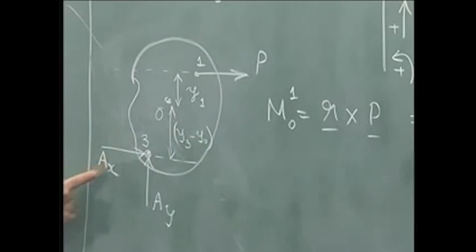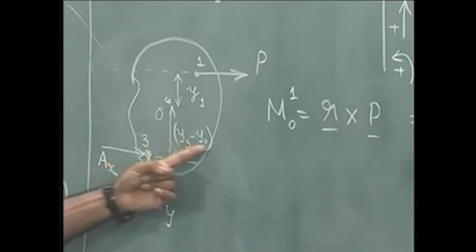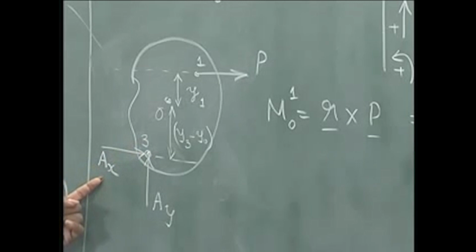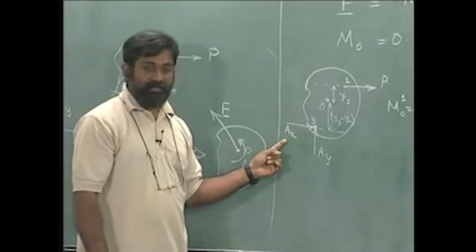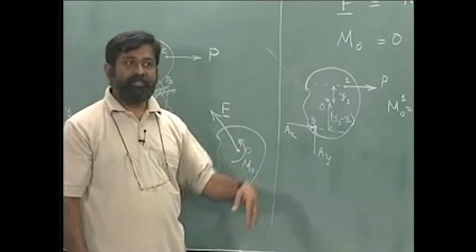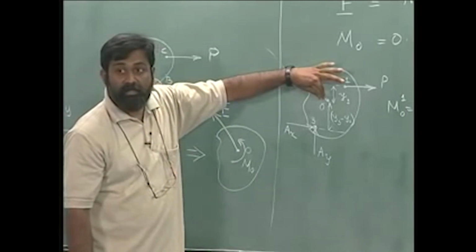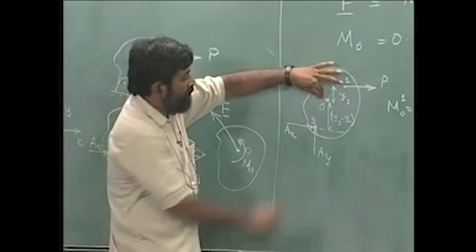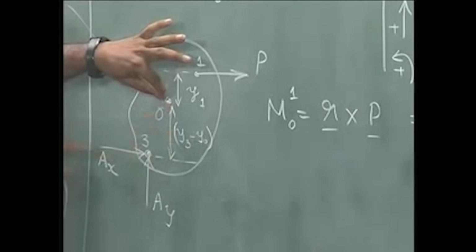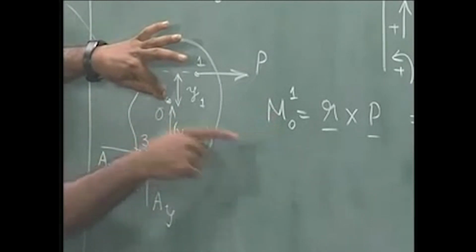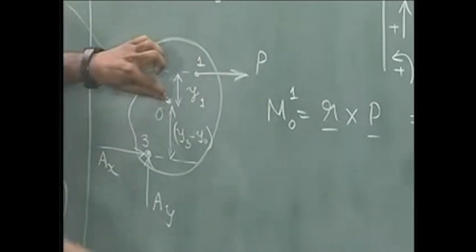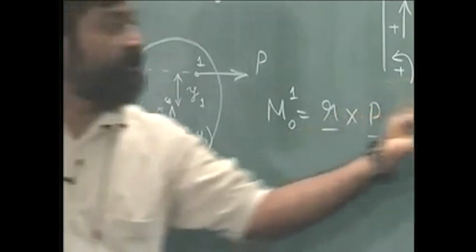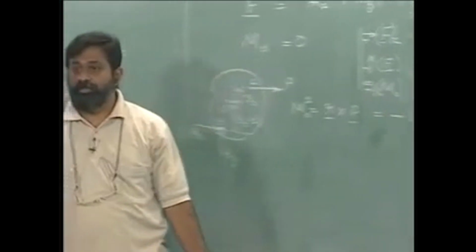Okay. And then I can multiply that with this Ax. Again, to make it very simple, I will physically look at what the direction is. If this is the positive distance and this is the way the force is acting, it is going to go anti-clockwise, which means in this particular equation I will have it as positive.